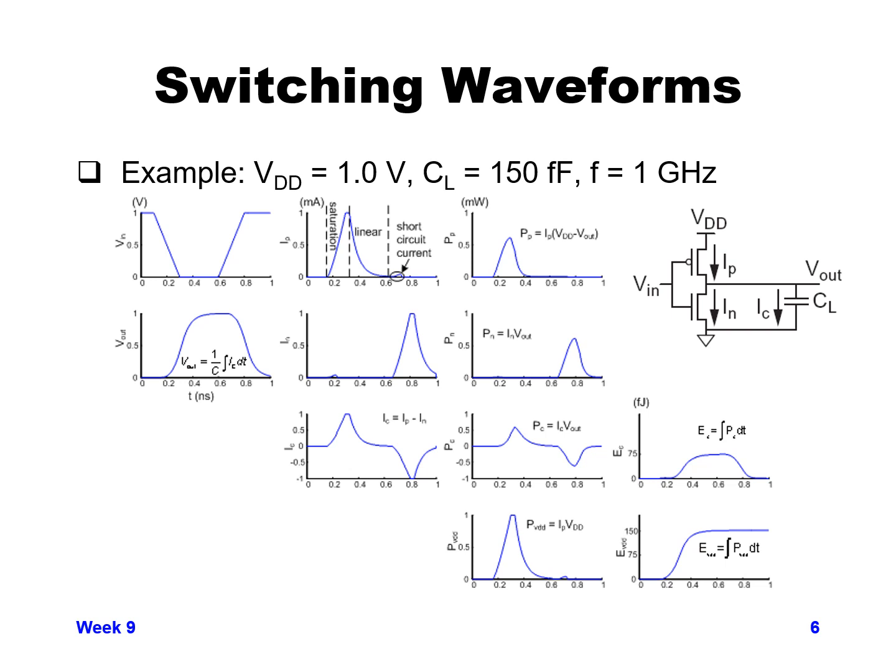And then finally, on the third graph down, you can see the current through the capacitor initially starts at 0. As you're charging it, you go to a positive current and then it decays back down to 0. And then as you're discharging it, it goes to a negative current and then decays back up to 0.